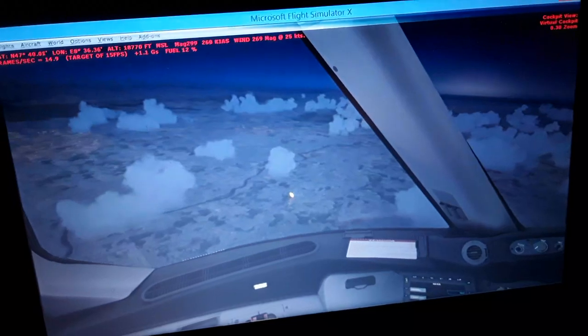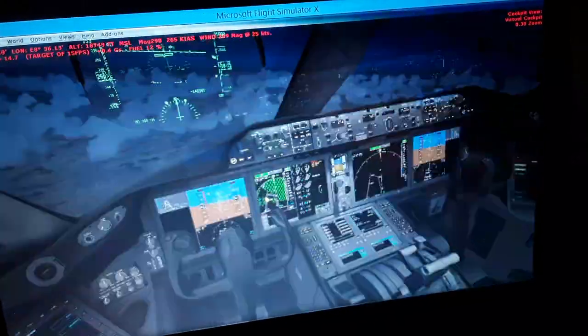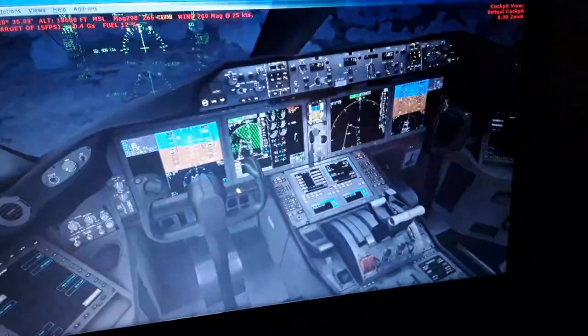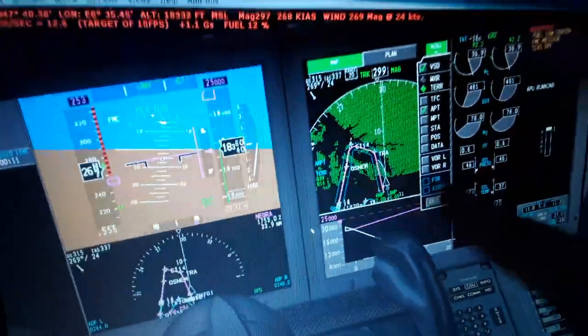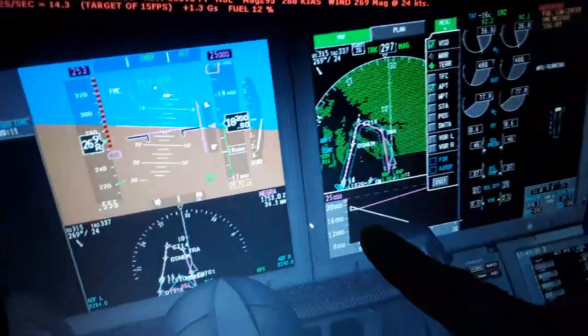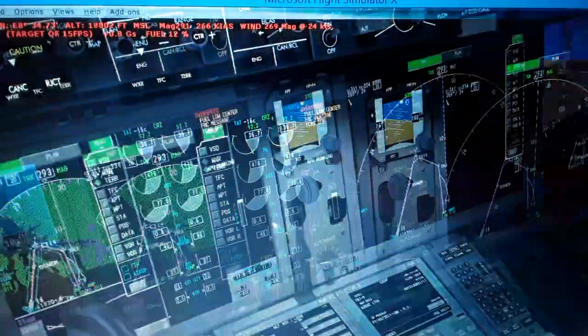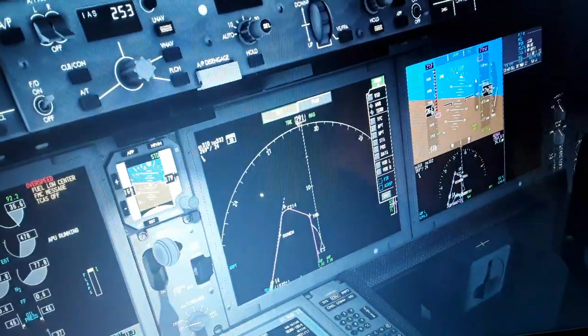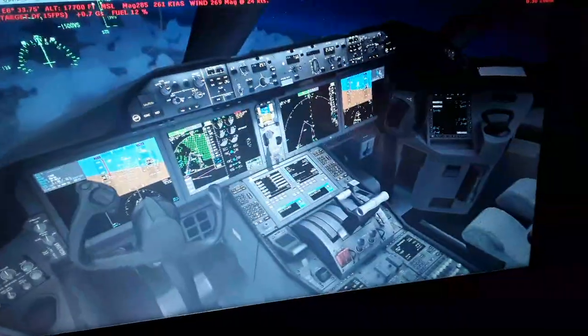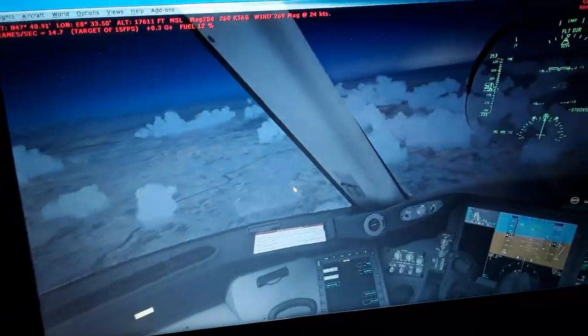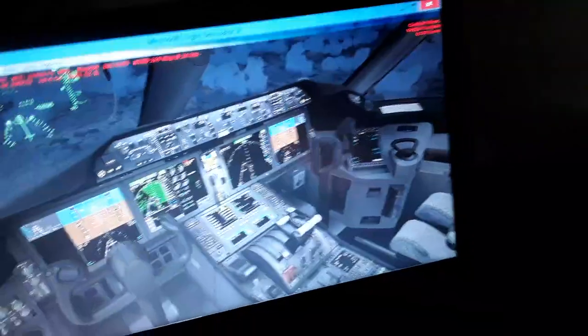And we have 5 more minutes to descend, approach and land. We need to follow this plan, the purple line, as you can see, and now the other side, also the autopilot settings we have for approach and landing. So we may initiate the descent now, the turn, in a couple of minutes.